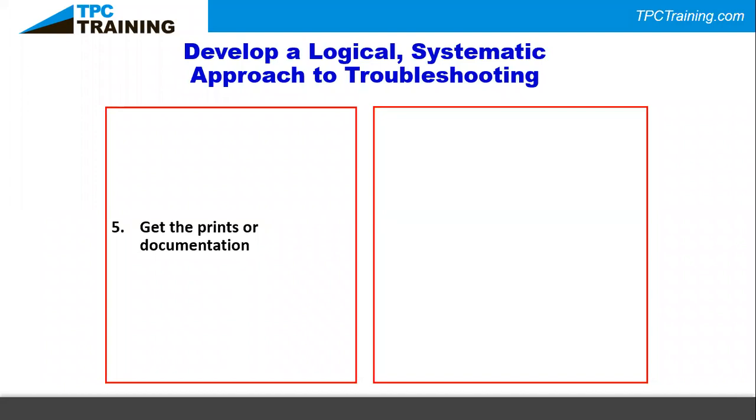So on the print side, another thing to be very aware of, especially if you're on the electrical side, is NFPA 70E, which is our electrical troubleshooting standard and electrical arc flash safety standard. It says that facilities must have up-to-date prints and documentation of their one-line diagrams and their facility level diagrams. And what tends to happen is if those drawings are not up to date, you could actually get in some trouble with safety, because that's how important these documentations are.